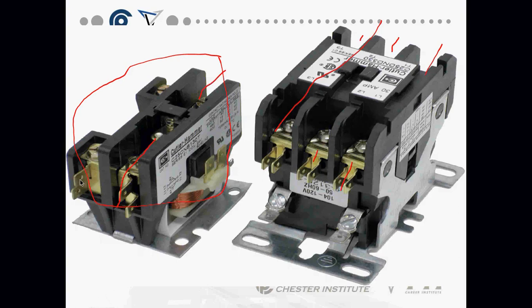L1, and then L2 doesn't switch. Remember I showed you that I said that's a pet peeve of mine because it leaves L2 energized. It's a safety issue, but be aware it's cheaper than having a double pole contactor. So L2 may come in on this side, it's always energized. My coils connect here, and you can't see it, there's another connection on the other side. In this case, my coil connects here and here.